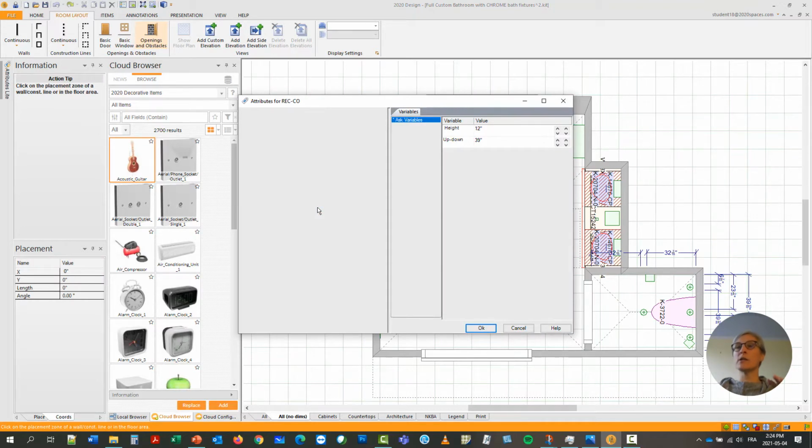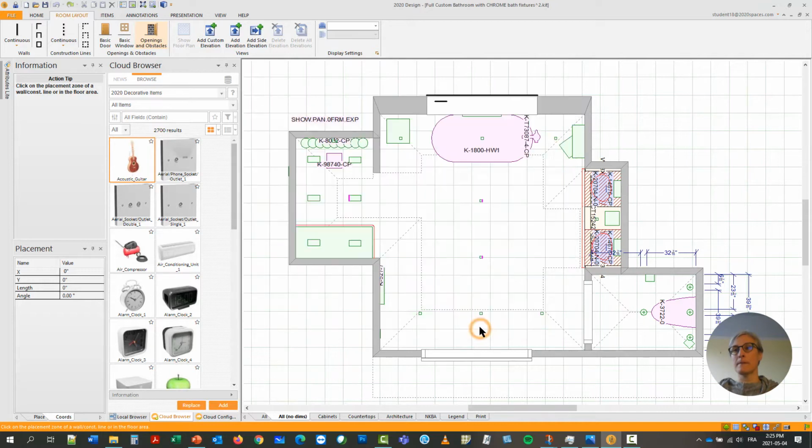and the cutout requires 2 answers. The first answer is how high from the floor the cutout will be. So it will start from the bottom of the floor until the bottom of the cutout itself. For this particular wall, I want a cutout that will be 48 inches from the floor. The height is the height of the cutout itself, basically the hole that we're going to create. 12 for this particular project is what we need, but it could be possible in your own projects you need to change that height. I will click OK, and now I have a tiny hole following this wall.